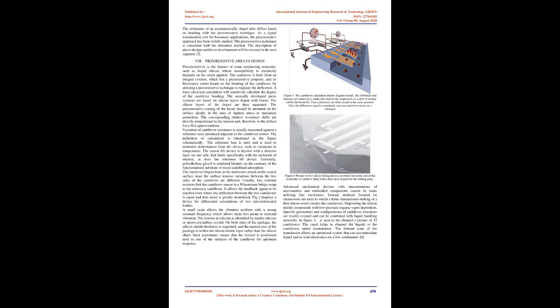8. Piezoresistive array design. Piezoresistivity is the feature of some conducting materials, such as doped silicon, whose electrical resistance depends on the strain applied. The cantilever is built with an integral resistor, which has a piezoresistive property, and its resistance varies based on the bending of the cantilever, utilizing a piezoresistive technique to regulate the deflection. A basic electrical calculation will sensitively calculate the degree of the cantilever bending.